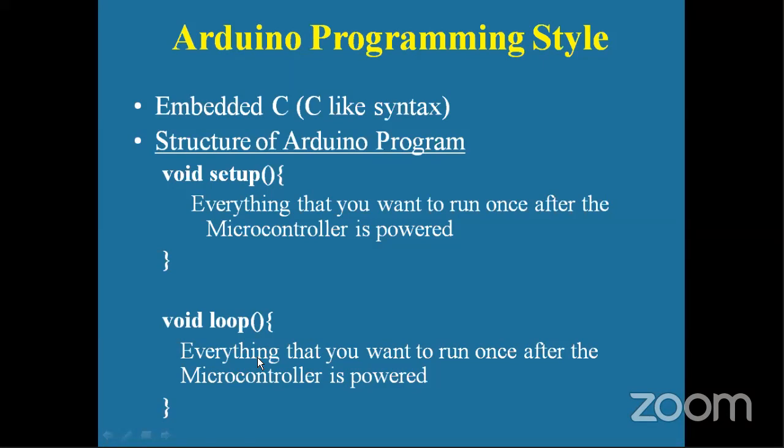It doesn't mean that you cannot write your own function. You can write your own user-defined function, of course, but these two functions are standard functions. You cannot have your own function called setup and then write some code into it. It is already there. The loop function is already there. You have to understand when these functions will be executed. The loop function will execute continuously as long as the microcontroller is switched on. The setup function executes only once, every time you start the microcontroller.